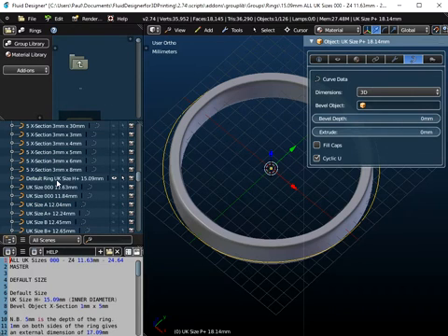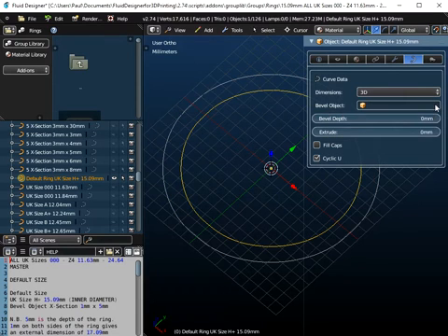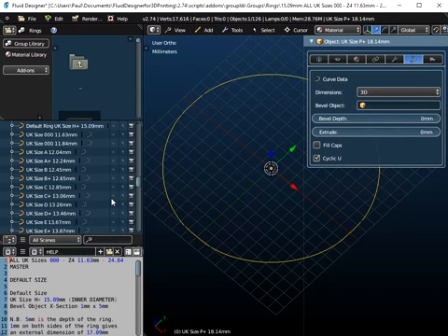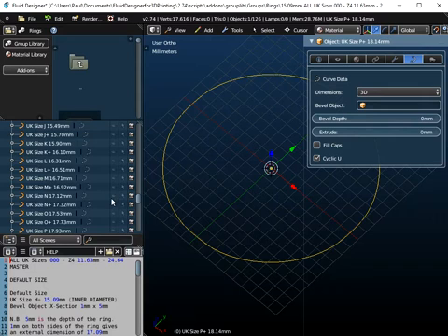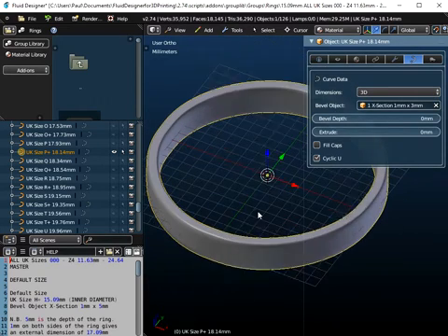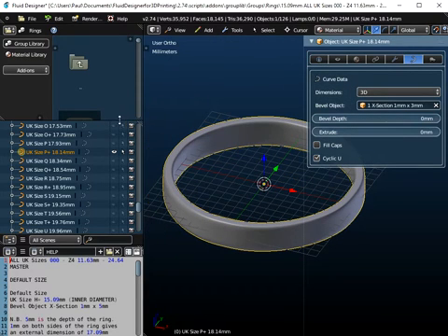But before we do that, what we must always do is to remove the bevel object, remove the cross section from the original default ring. You don't want to be printing two rings, so just remove that and just hide the original ring, the default one, because we're going to work with this size now, UK size P+. So we need to add some thickness to that, so I'm going to select a thickness of 1mm by 3mm. So it's 1mm thick here and 3mm deep here.